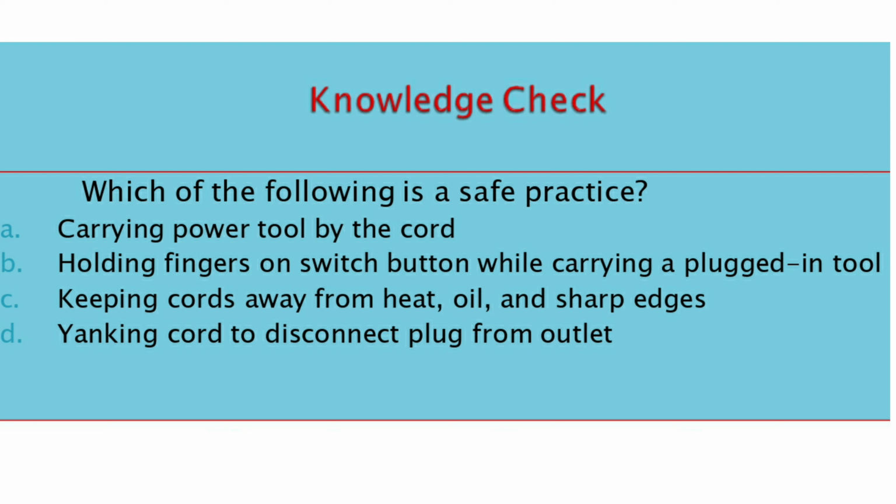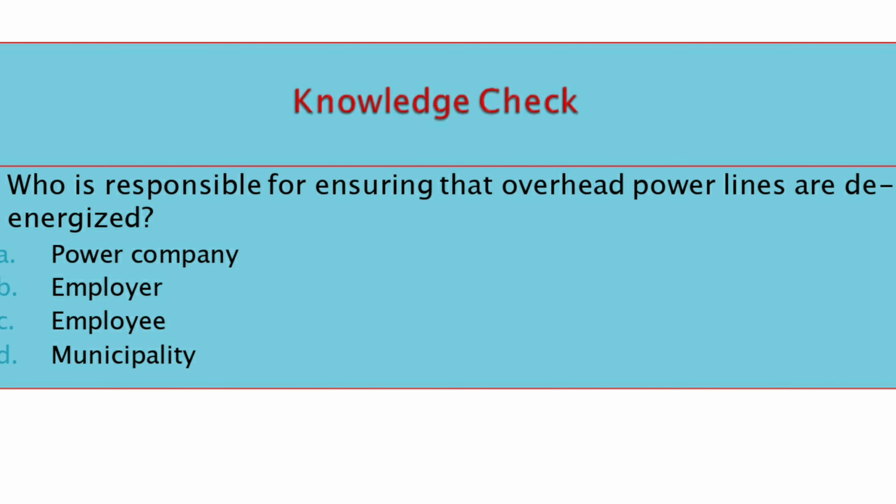Which of the following is a safe practice? A. Carrying power tool by the cord. B. Holding fingers on switch button while carrying a plugged-in tool. C. Keeping cords away from heat, oil, and sharp edges. D. Yanking cord to disconnect plug from outlet. Answer. C. Keeping cords away from heat, oil, and sharp edges.